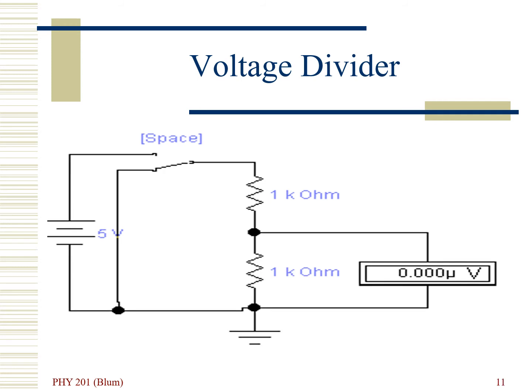The other possible 1-bit fraction is, of course, 0 in the halves place, which would be 0. So if we flip the switch down to low, then we are directly connected to the ground on both sides of the circuit. So we're putting in a low, so there's just no voltage going in the circuit whatsoever, and we get a 0 out. So previously we put in a high representing the halves place, and so we got half of our voltage, and now we are putting in a low, and we get nothing, we get a low. So we've achieved what we wanted. We have a 1-bit fraction, which is either half or 0.